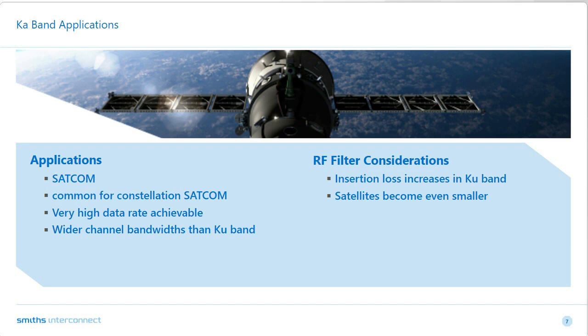for the Ka band. The performance of the RF filter is another key decision in the overall system. Waveguide filters do become smaller with increased frequency, but are significantly larger than printed filters in this band. The improvements in low noise amplifiers in this band make the smaller size of the printed filters much more attractive.